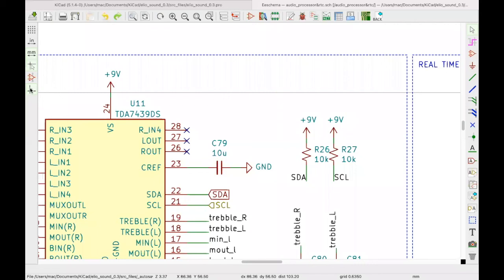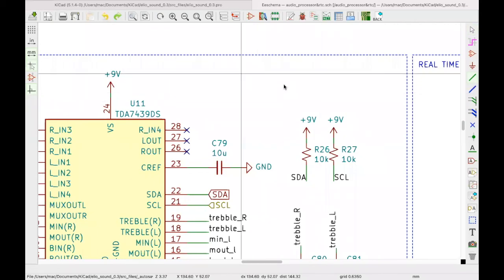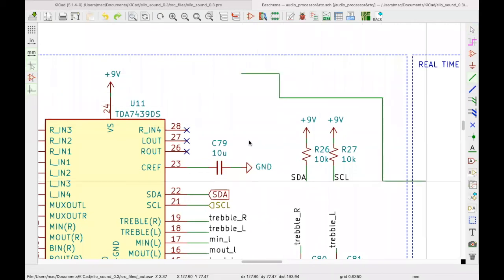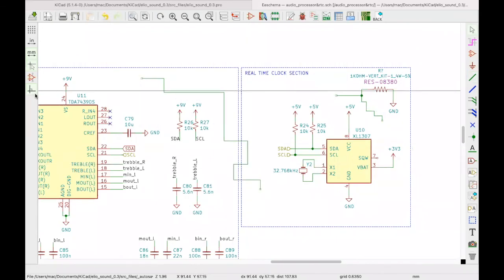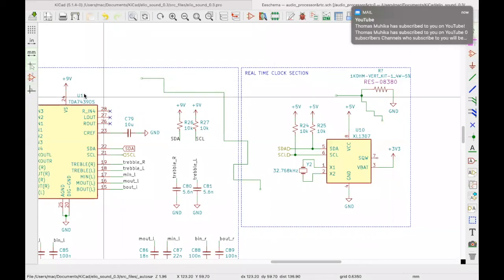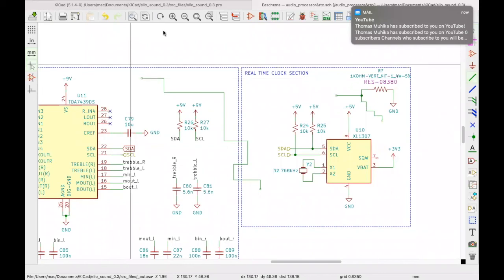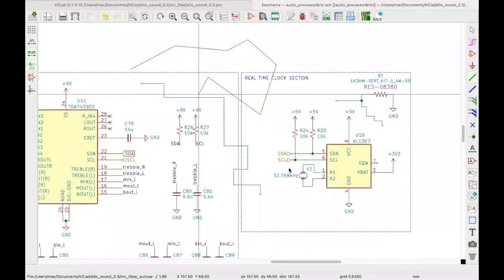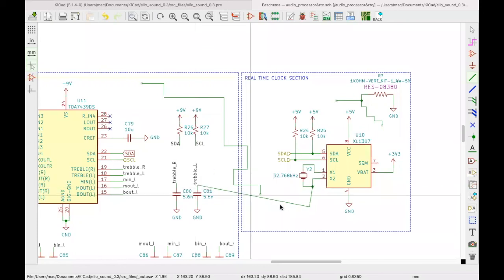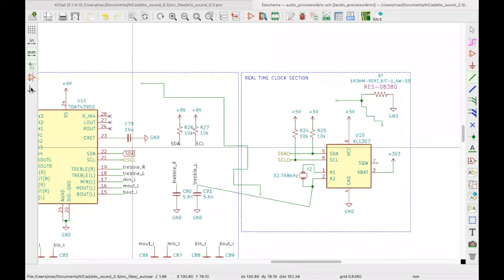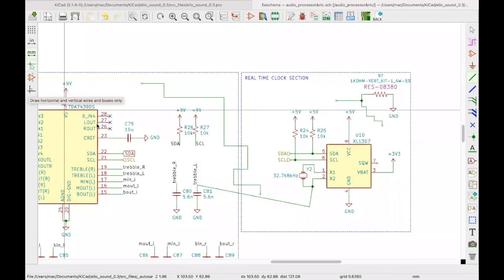So for this one, when you draw your wires here, you realize that they are at 90 degrees. You may mess up your KiCad one day and click on this command here accidentally, and then you wonder what's happening. So this particular tool is for that. When it's that way, I can't draw wires at 90 freely, so I'll have to make sure I'm putting them at 90, and I can draw weird angles, say of the wire. Say you want to connect something and you want to draw some weird connection like that one. It's only possible when you disable this one here. But of course, I want to go with 90 degrees here.